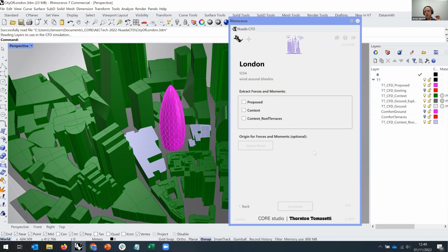your repetitive floors, and I think it would be pretty amazing to maybe start in Rhino or even start in ETABS, but then when the simulation is done, you basically in ETABS pick up the results, because that's the other thing an app like this allows you to do, to start in one software and pick it up in another software. So for instance, start your model in Rhino or in Revit, run the simulation. When the results are done, get it into ETABS and get your loading per floor or something like that.